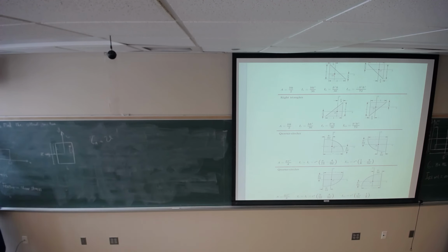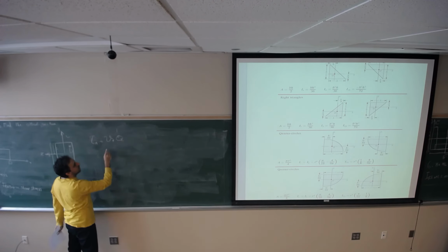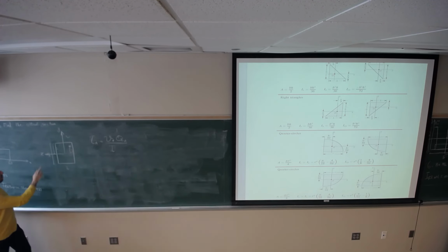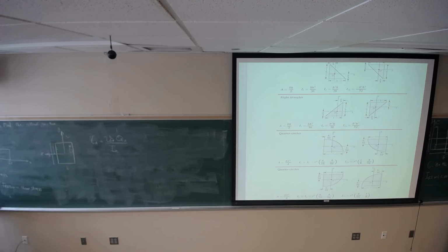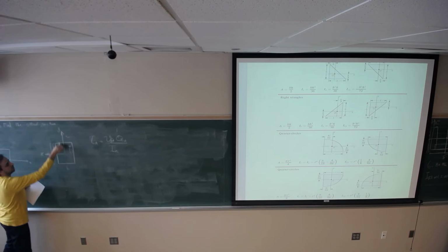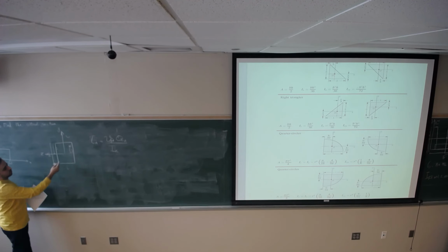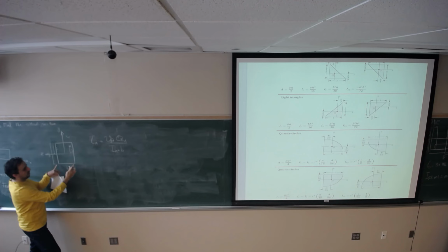We can find it by looking at the shear force diagram, times Q, I will talk about Q, divided by I with respect to Z. The shear force is in the Y direction, but the I that you are using should be about the other axis, which is Z, times B, this length.